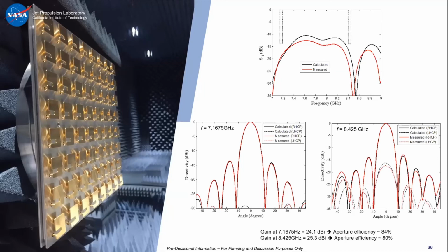In that case, for the Europa mission concept, since we wanted to check the performance of this antenna at cryogenic temperature, which is lower than -170 Celsius, we're actually doing a radiation pattern measurement at cryogenic temperature as well. We're putting it in a foam enclosure that will not interfere with the RF performance, and we will use liquid nitrogen to go to this cryogenic temperature. In real time, we'll get the radiation pattern and gain of this antenna. That's how we're qualifying it. This is a great setup for making the measurements for this particular one. I think it will go a long way. Exactly, because of getting such antennas for future missions. Thank you very much. This is Mahadevan from ISRO. Thank you.